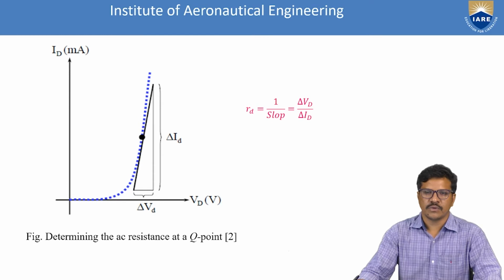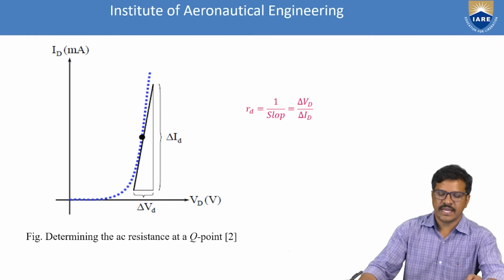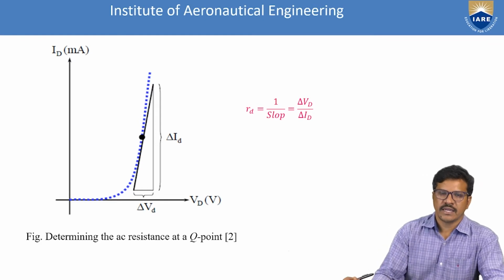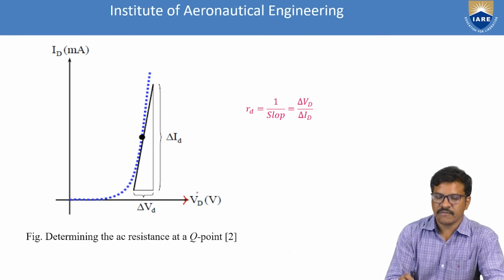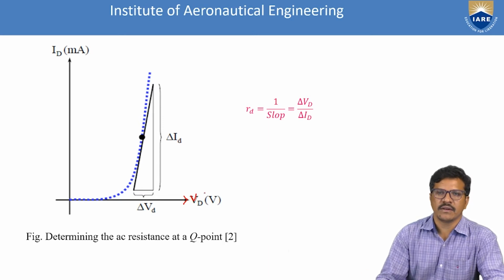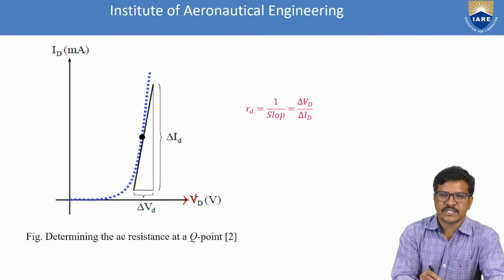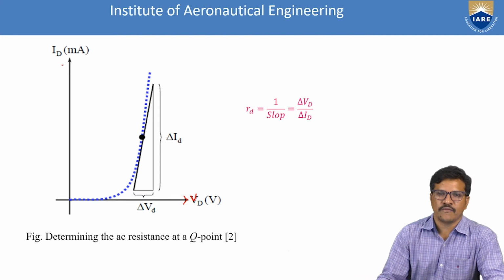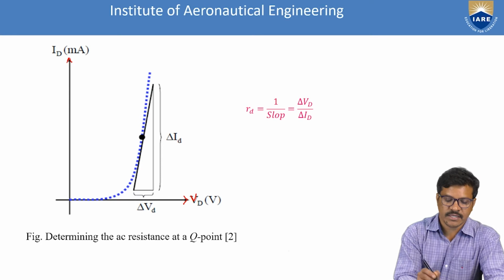There are two basic characteristics, forward and reverse characteristics. In the characteristic curve, the x-axis represents the volts provided by the external voltage to the diode, and the resultant current that flows inside the diode is measured on the y-axis.